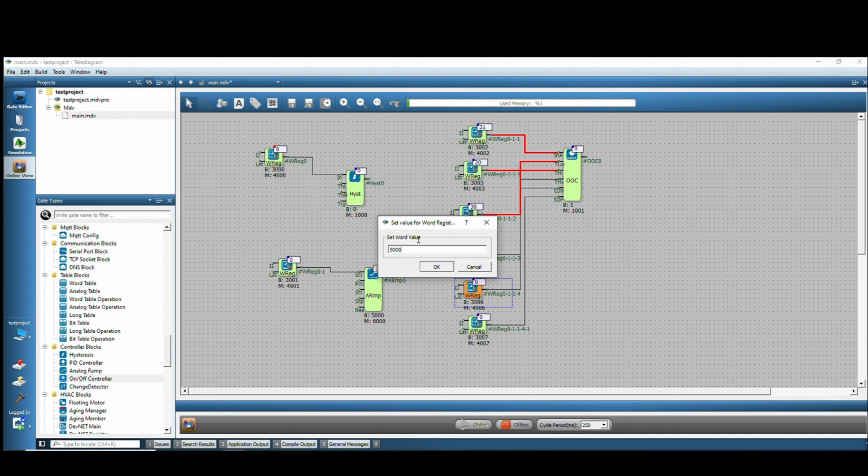Let's enter 5 seconds for the alarm turn-on time. Let's also define the turn-off time. Let's enter that as 3 seconds. For example, we sent the expression 25. As you can see, it did not turn the output to 1. It waits for 5 seconds and turns the output to 1 at the end of 5 seconds.